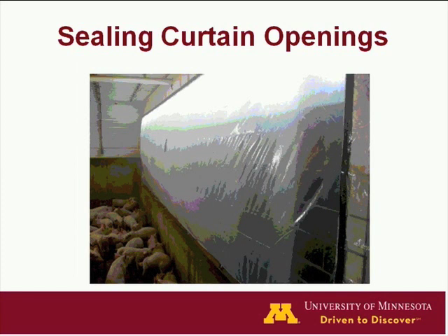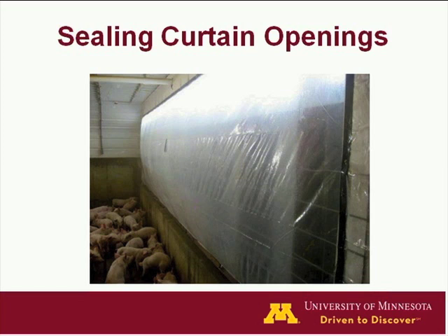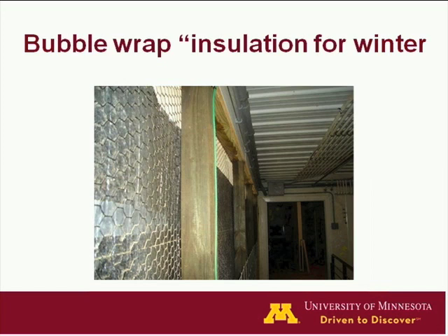Here, sealing the end wall of a tunnel ventilated barn is oftentimes a good idea in the wintertime if that end wall curtain is not going to be used at that time, or the use of this bubble wrap insulation for winter on the inside can be effective to not only seal up the curtain but also provide a little bit more insulation and keep that surface from getting wet again. Similar conditions to what we talked about with the concrete wall.